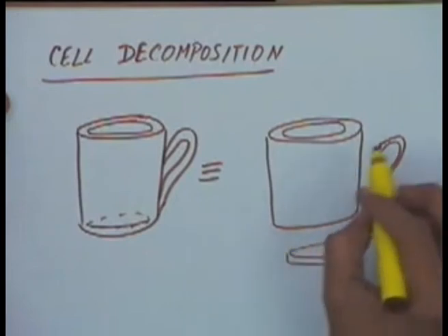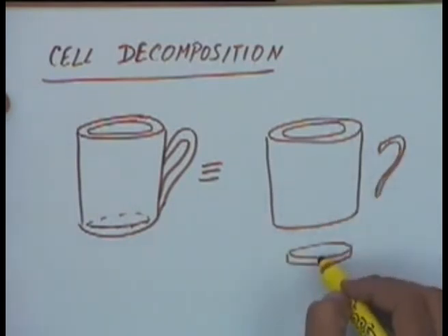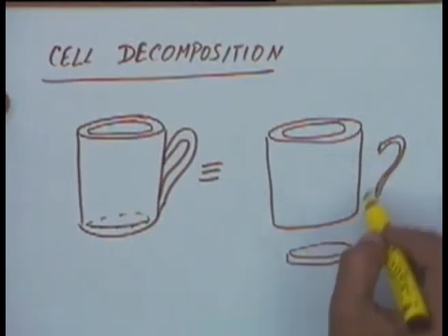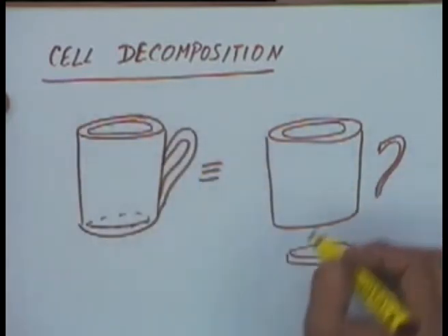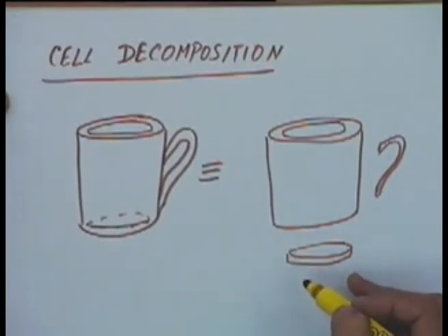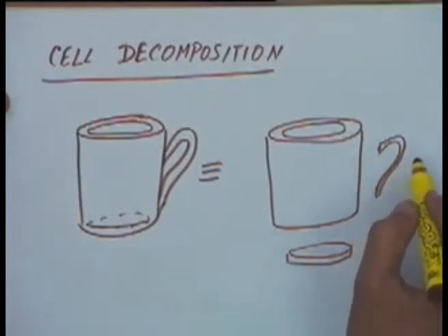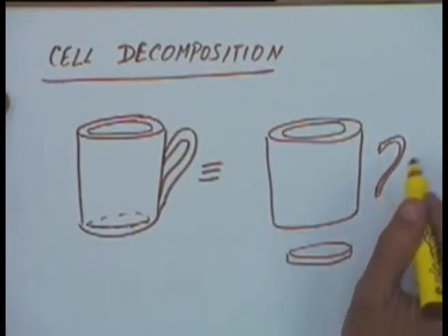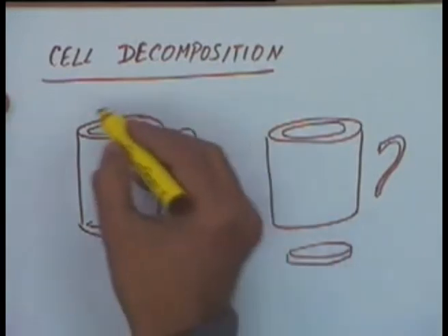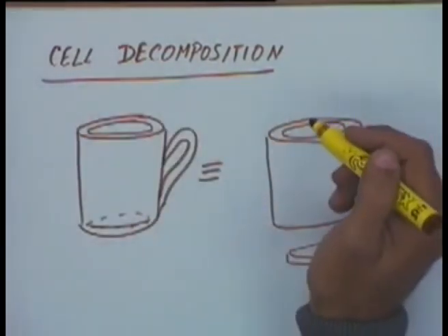In this method, the intersection between any of these solids will always be 0. We ensure that there is no intersection between these. We are just decomposing this solid into a set of smaller or simpler solids. Then each of these solids can again be further decomposed if need be. But we will not have any intersection between 2 primitives. So for creating a solid like this, we are in effect starting from the initial solid and then decomposing it.